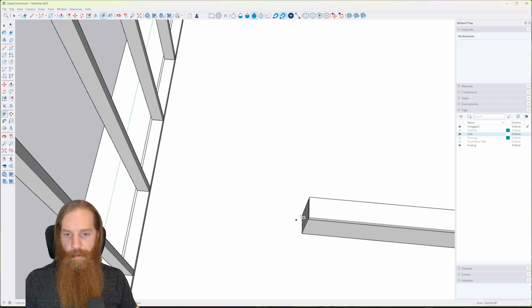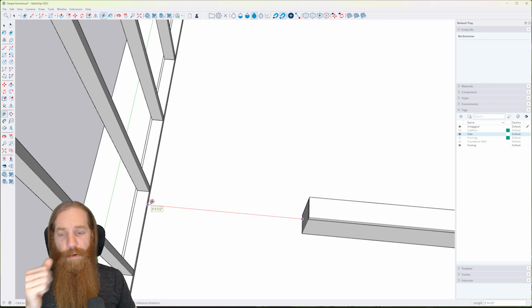Now that we have the exterior walls in, it might be a little small. We wanted to fit, I think I was doing a 36-inch door here, so we need 36 inches plus 2 inches for the rough opening on the width. So we're gonna be at 38, and this opening is currently a 39.5. It's a little small. It's not going to leave us any room for trim.